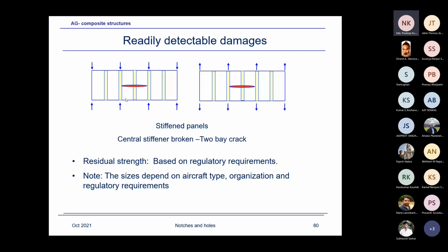And sir, on the left side you have shown the compressive stress, right side tensile stress. Well, this is compression, this is tension. Yes, compression also causes failure of a composite. It's not like metal, by the way. If we are dealing with composites, they are more critical in compression with the notch. One would assume a crack will close and it doesn't fail. But unfortunately, compression has a lower strength than tension for the cracks.